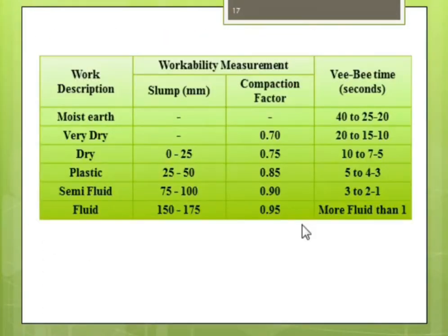So these are the general values given in a book, with reference to how we can check whether our concrete will be good or not in terms of rheology or workability. For slump value, there are the compaction factor and VB consistometer tests. These are not standard values, just a guideline to finalize whether our concrete achieves the desired workability or not.